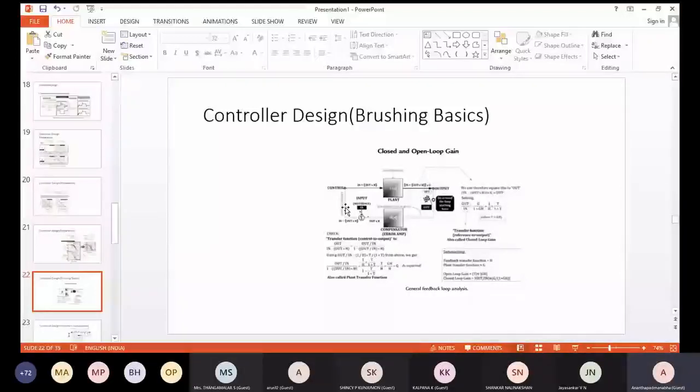This is supposed to be the actual controller, and it serves the purpose of maintaining the output voltage regulated, irrespective of disturbances. If you go through the very simple mathematics shown on the slide, you will come to the conclusion that the loop gain has to be as high as possible.